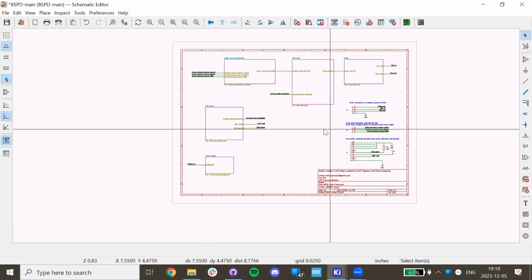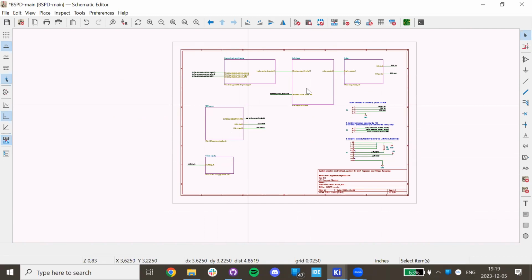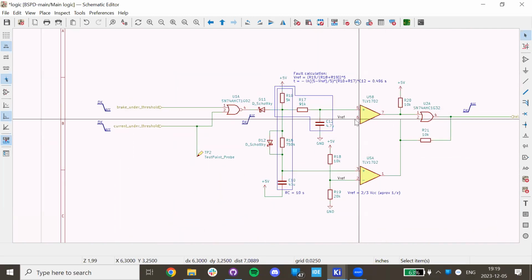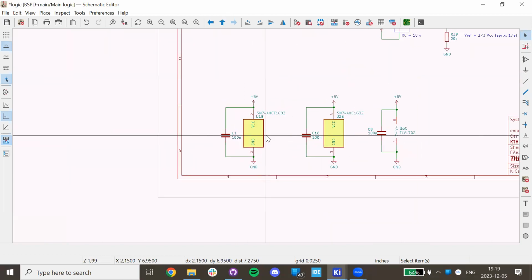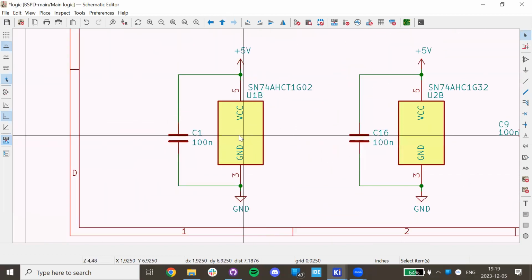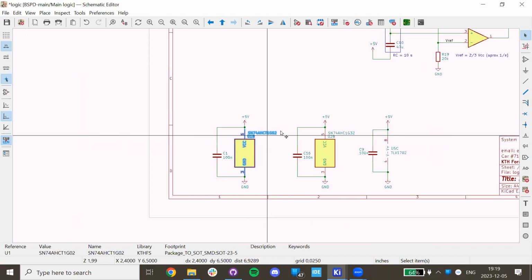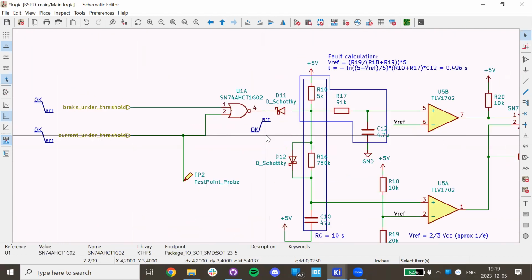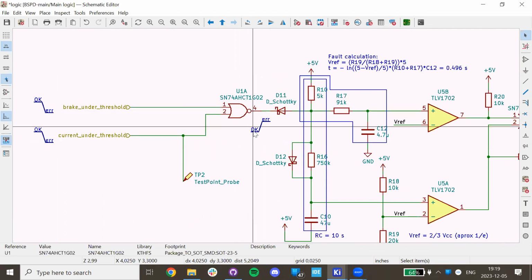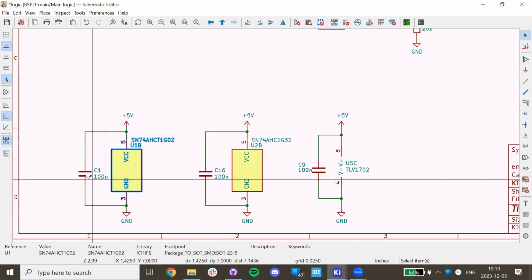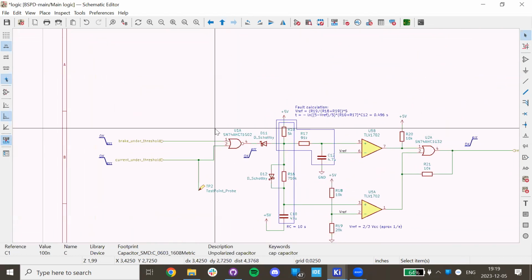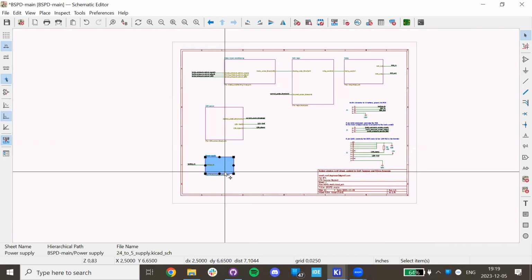And usually, if you have some component, like an op-amp or an MCU or something, it has a power supply. So this is the power part of U1. Okay, it's the NOR gate here. This is the power of the NOR gate. Then I know that C1, for example, should be close to the OR gate. But we'll go through that later.